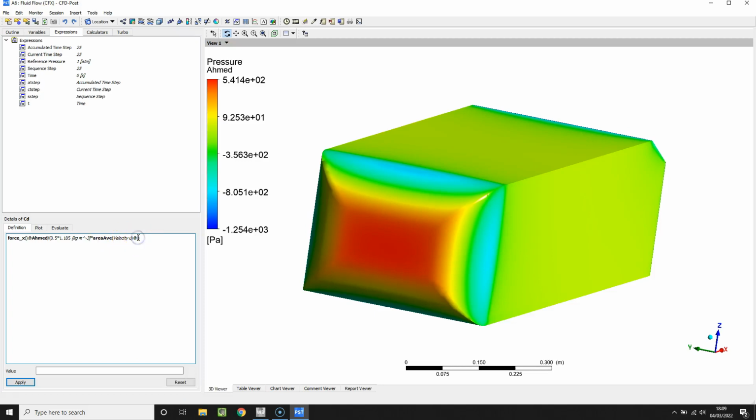where we want that is at the inlet. So just right clicking, locations, and inlets there. If you use the right clicking and use locations, you'll always get the correct spelling for the boundary conditions, so that is advised. So just selecting this group for the velocity and putting the square on that,